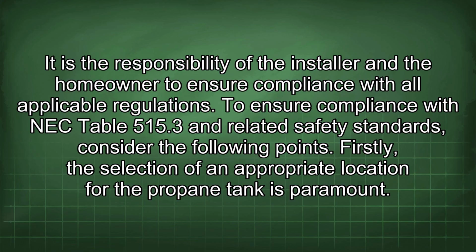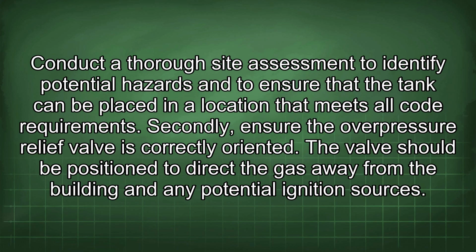To ensure compliance with NEC Table 515.3 and related safety standards, consider the following points. Firstly, the selection of an appropriate location for the propane tank is paramount. Conduct a thorough site assessment to identify potential hazards and to ensure that the tank can be placed in a location that meets all code requirements. Secondly, ensure the overpressure relief valve is correctly oriented. The valve should be positioned to direct the gas away from the building and any potential ignition sources.